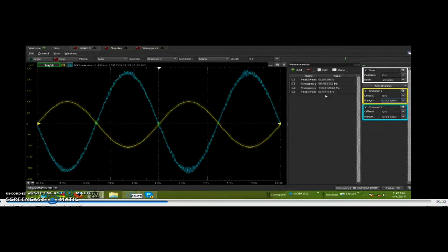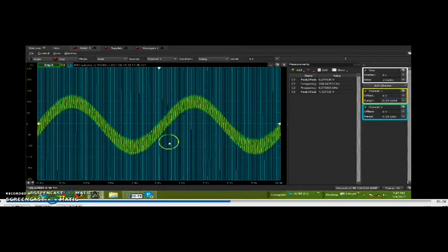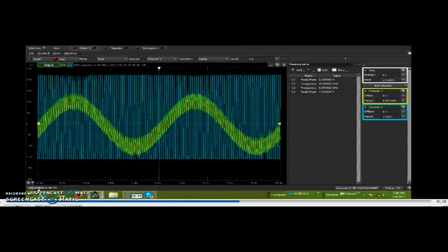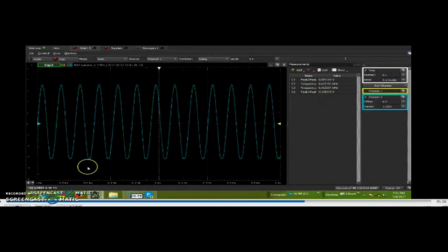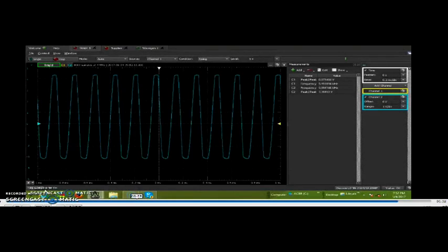As long as the gain of the amplifier is less than 3, the system will be acting like an amplifier. If the gain becomes equal to 3, the system will start oscillating with a frequency of 6.3 kHz, even though the input of 100 Hz is applied. When the gain is just equal to 3, we are getting 6.4 kHz even without the input waveform. If the gain of the amplifier becomes more than 3, now you can see on either the positive or negative peak, it gets clipped off. Now the system is in an unstable condition.